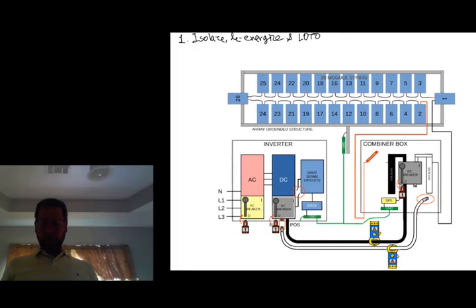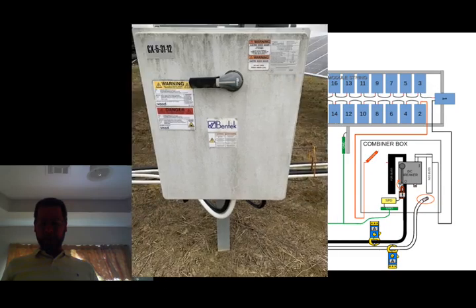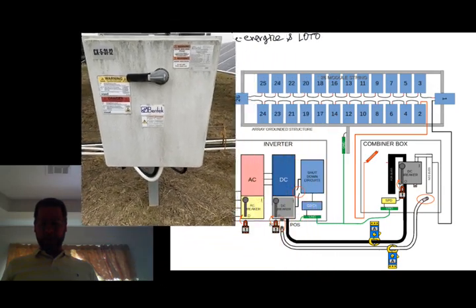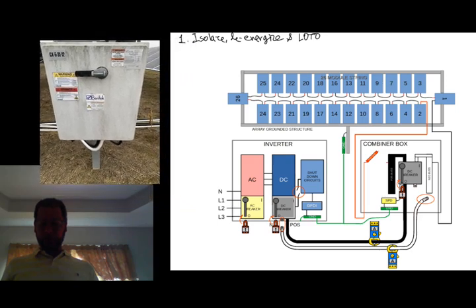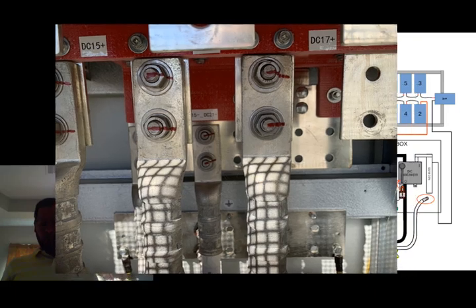Before you begin, open or turn off each load break rated disconnect in the system section you'll be working. Isolate each conductor from electronics and other conductors. You may have to remove the conductor from a terminal.